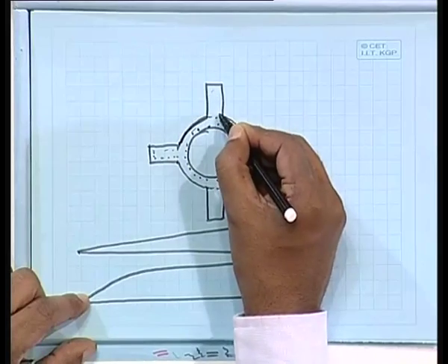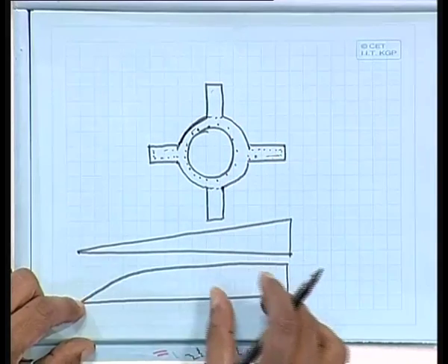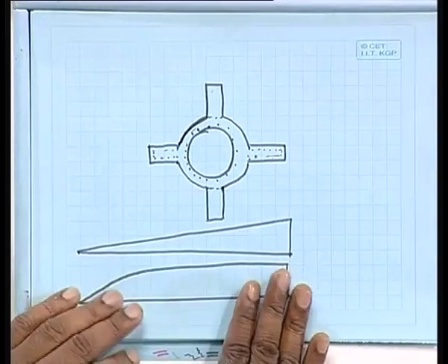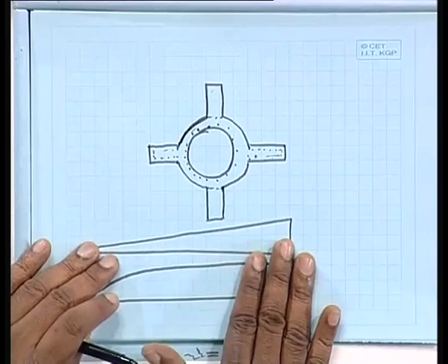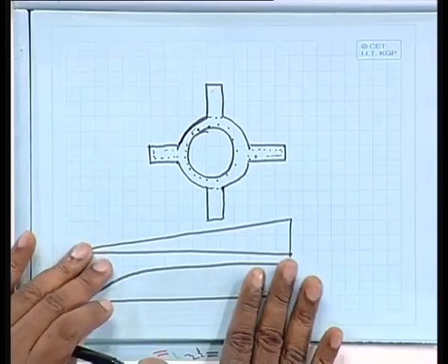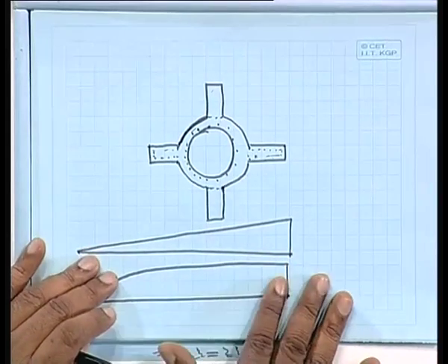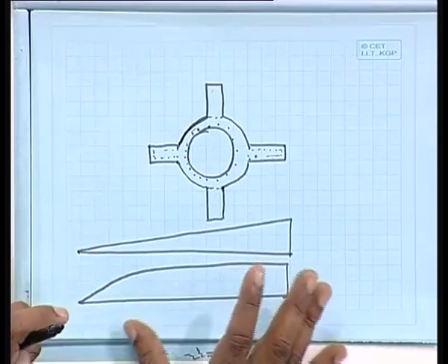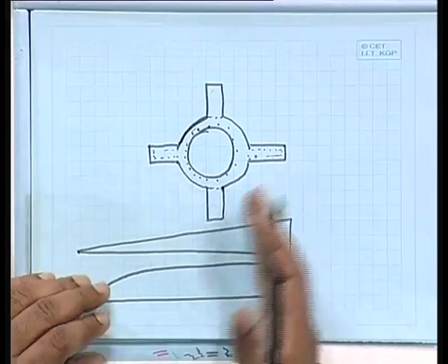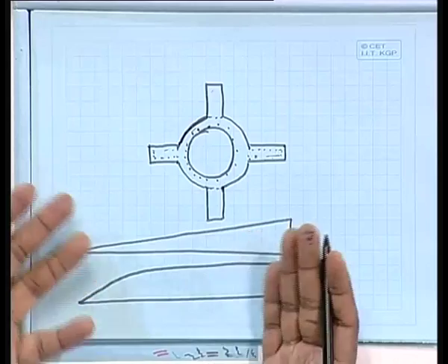Similarly, for this one also. So, wherever you have the stress diagram, if you can understand the stress diagram and strain diagram of the limit state method of concrete design, immediately you can find out the moment capacity and axial load capacity.